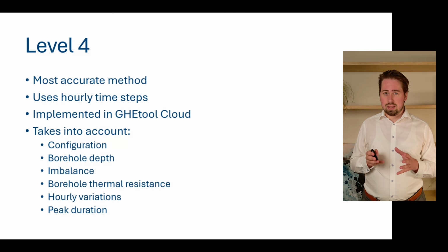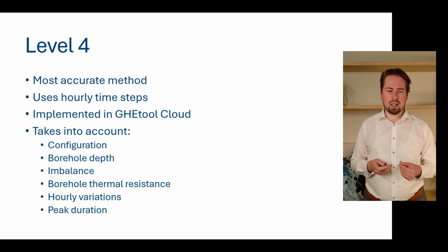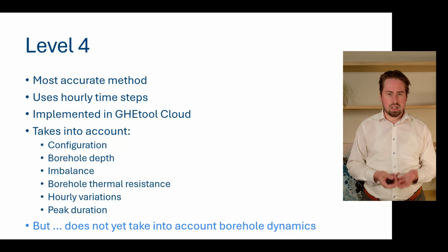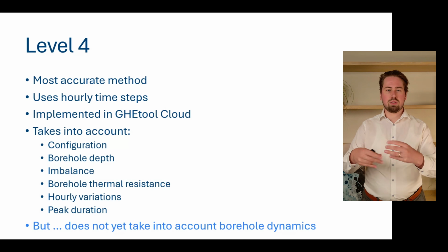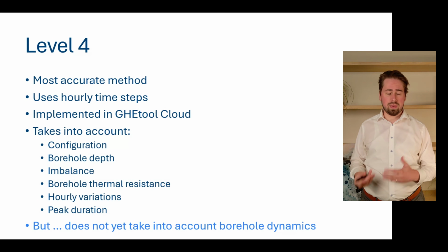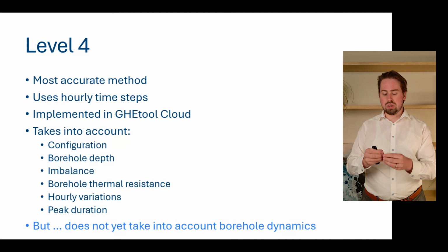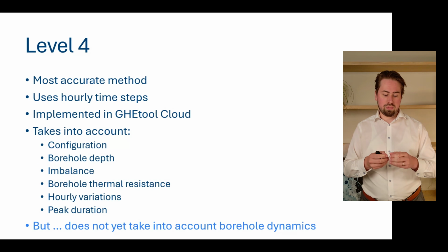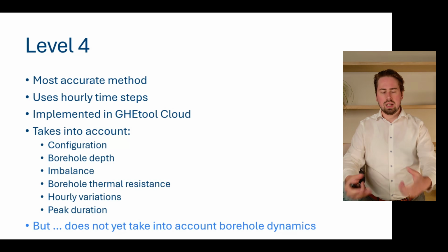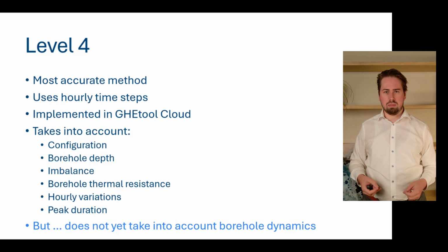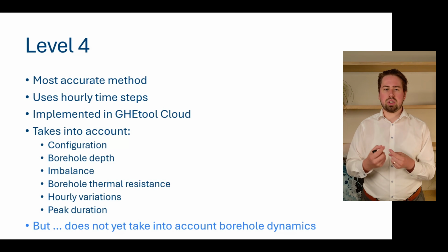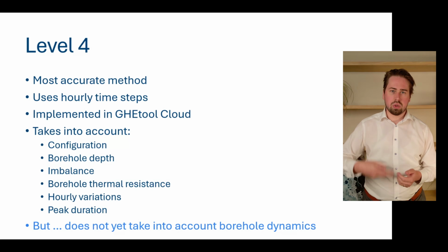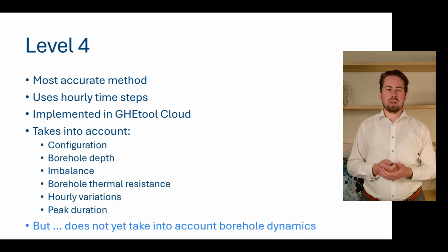The only downside of this method, and now we're getting a little bit technical, is that we do not yet consider the borehole dynamics. Working with the effective borehole thermal resistance is a steady state approach, and we already covered that. But in fact, there are also some transient effects. When you extract heat from the borehole, it's first coming from the fluids, and then from the grout, and then from actually your geothermal bore field itself. This thermal inertia is not yet taken into account, but we are constantly working with universities to also make this more accurate. So that's something to come.